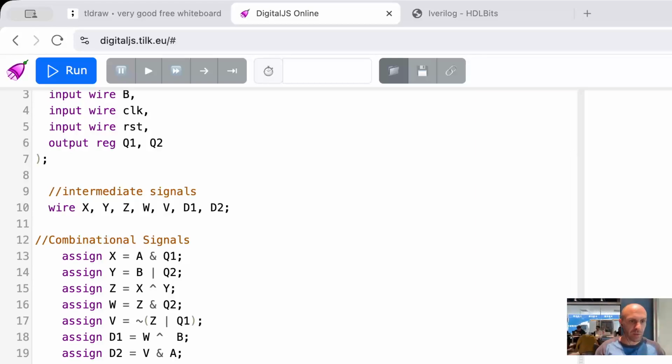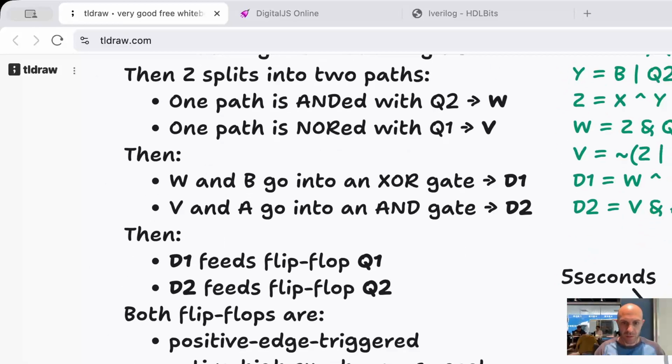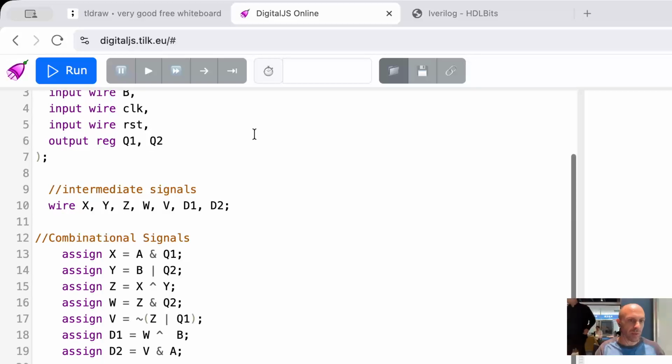So what that means is we're going to set the state to 0 on the reset. So when the reset is high, because it's active high, we're going to set it to 0. That wipes out any of the values. It's like starting from a clean slate, literally.